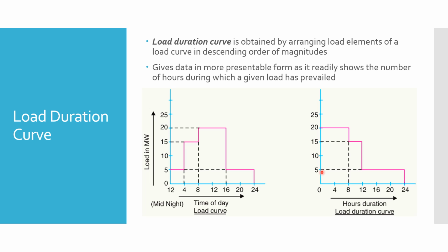Why are you not opting to turn off the thermal power plants? Because their startup time, as I have told you in the steam power lectures, is around 8 hours. So once you shut them down, you cannot harness electricity from them for another 8 hours, and that startup process also takes up a lot of money and a lot of energy. So that's a waste of energy. So in general, we like to keep our coal-fired power plants in operation unless they have to be shut down for maintenance.